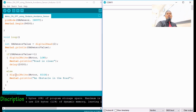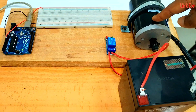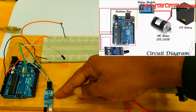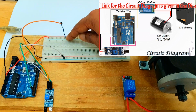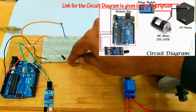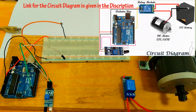Now we will make the connections according to the circuit diagram, upload the code, and we will control the motor accordingly. This is the motor which we are going to control. This motor is connected to the battery through a relay module. This is the IR based obstacle avoidance sensor. The first pin is the VCC pin connected with the VCC line of the breadboard, the second pin is the ground pin of the module connected with the ground line, and the third pin is the output pin connected with the second pin of the Arduino Uno board.